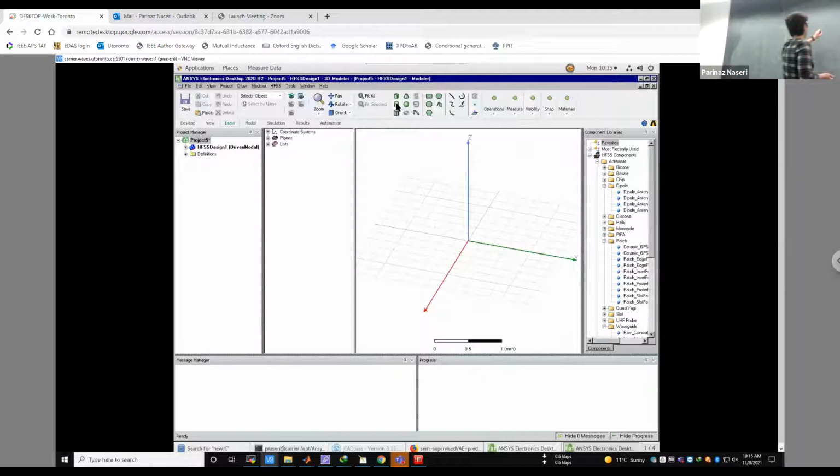You can also go with a realistic one. Let's say you have 2 cylinders and then you have metallization, like copper, things like that. But because it's going to be a realistic case of copper, it tries to solve inside as well, because E is not exactly 0. It's very close to 0, but it's not exactly 0. So it would take time to solve it here.